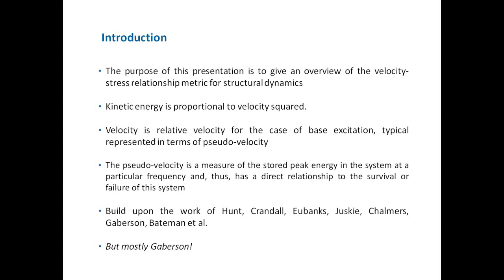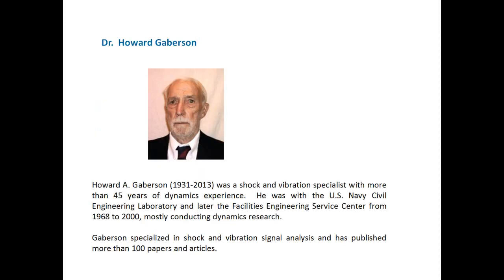And sometimes we'll say pseudo-velocity, which is roughly equivalent to the relative velocity. We use those terms kind of interchangeably. The pseudo-velocity then is a measure of the stored peak energy in the system at a particular frequency, typically one of the natural frequencies, and thus has a direct relationship to the survival or failure of that system. This unit builds upon the work of Hunt, Crandall, Eubanks, Juski, Chalmers, Gaberson, Bateman, and others, but most particularly Gaberson, who was the champion of this method.